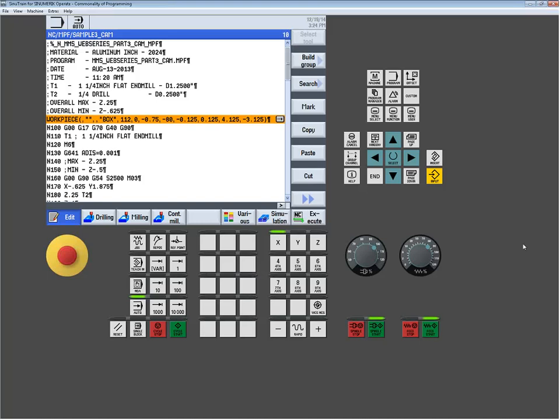Here's one. Can I use ISO mode for 5-axis programming? Okay. That's an area that I would start to enter with caution. Once you get to 5-axis, you have a lot of advanced cycles potentially being leveraged. In our world, TRAORI, which is your rotary tool point compensation, CYCLE800, which is your rotary workpiece compensation, ORIVECT, ORIAXIS.